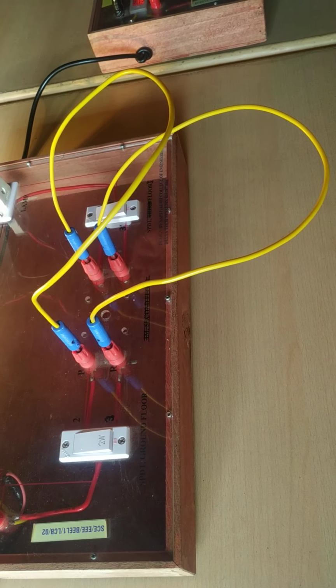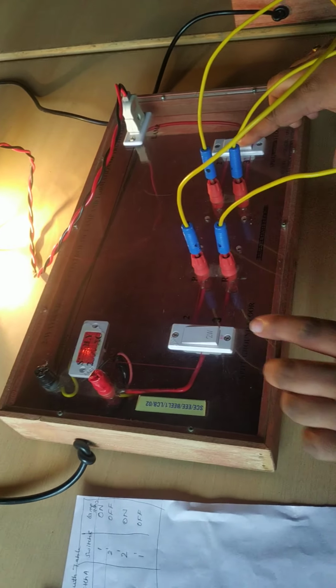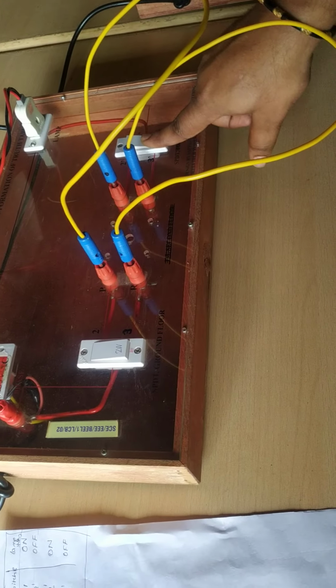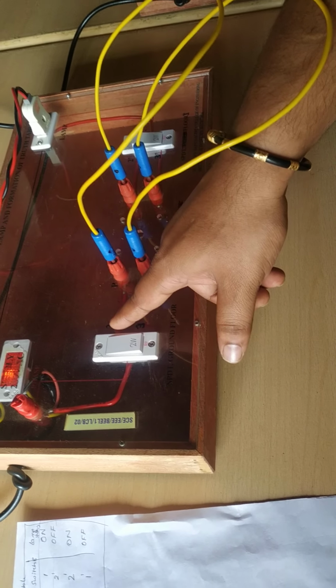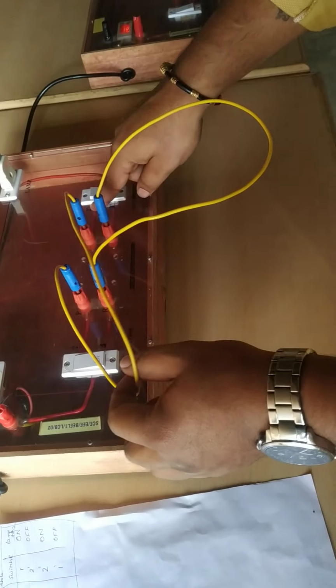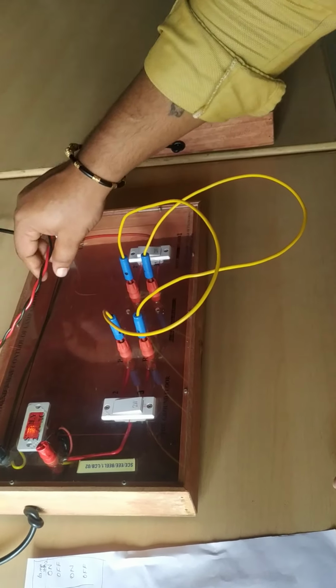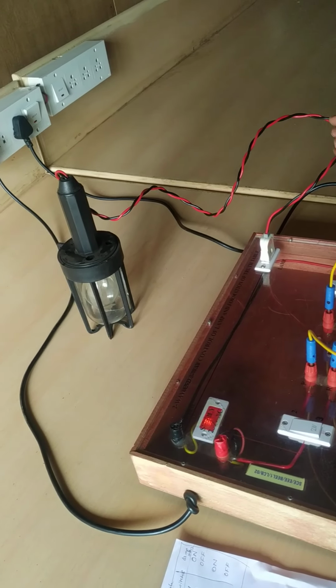glowing. In the same way, I'll keep the switch A at one position itself. I'll change the switch B to 1 dash terminal, 2 dash terminal. Therefore, from A position it comes to this wire. Through this wire it comes to switch B. But switch B is in 2 dash position. Therefore, it becomes open circuit. Therefore, the lamp is not glowing.